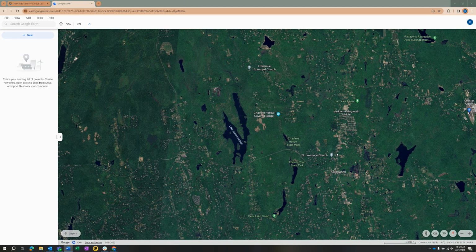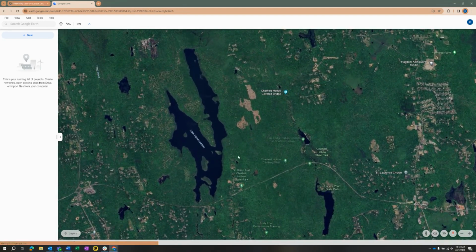And of course, this is a process that would usually probably be done with a lot more analysis by a civil engineer. PV Farm does not have GIS capability. So for this, we're going to be doing it on the fly and get some general boundaries going. So the first thing we're going to be doing is drawing inclusion and exclusion zones. Inclusion being these nice big areas we see here where we can put stuff. Exclusion being areas like this lake here, where we're probably not going to be putting any solar arrays on top of.